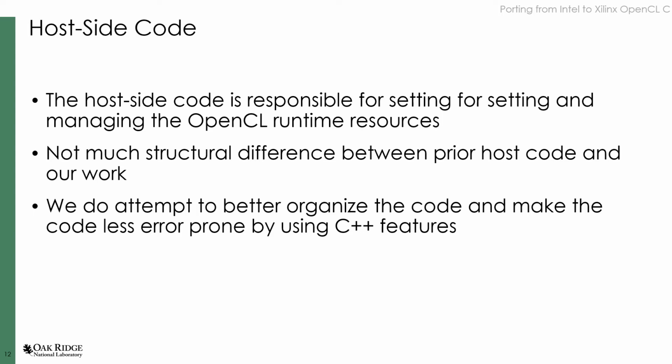A convenient feature of using OpenCL in our evaluation is that the structure of the host's code largely can remain the same even though we are evaluating a Xilinx FPGA. A salient change that we do make, though, is to leverage C++-like objects and to utilize the concept of resource acquisition as initialization, since most of the code is written using C-style constructs, but is compiled using a C++ compiler.